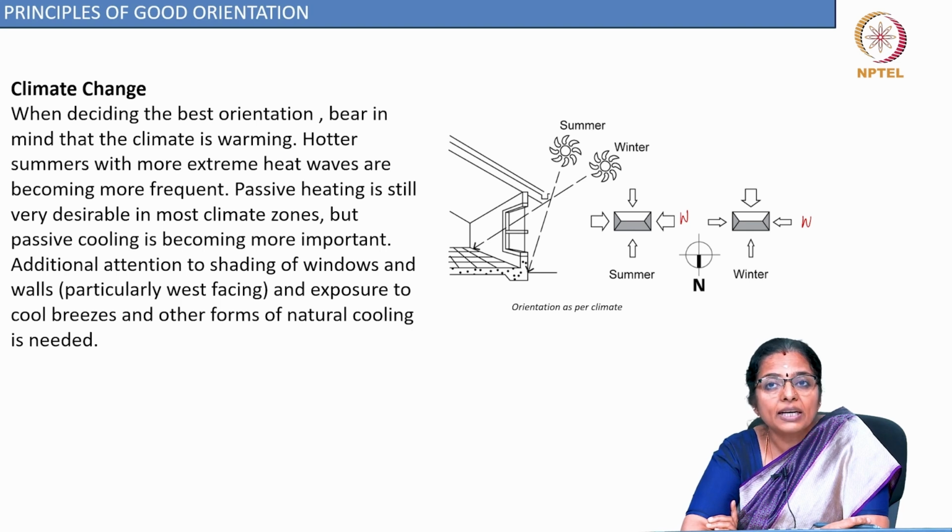Due to economic constraints, passive cooling has to happen in a natural manner because use of air conditioners may not be possible by all. Additional attention to shading of windows and walls, particularly west facing, and exposure to cool breezes and other forms of natural cooling is needed.